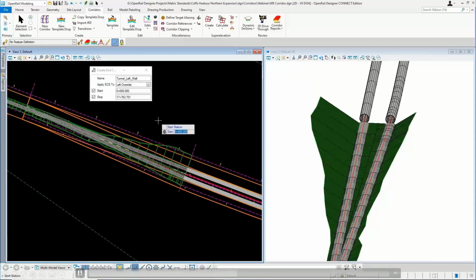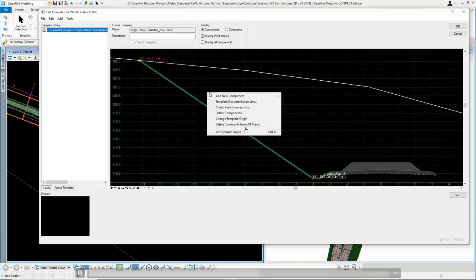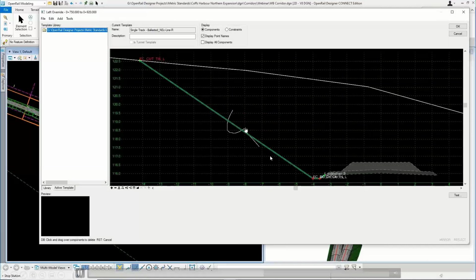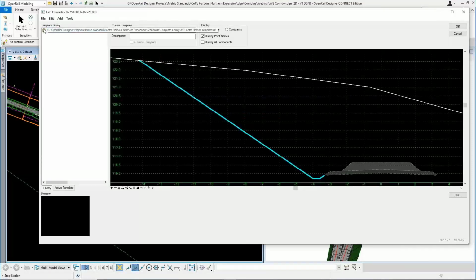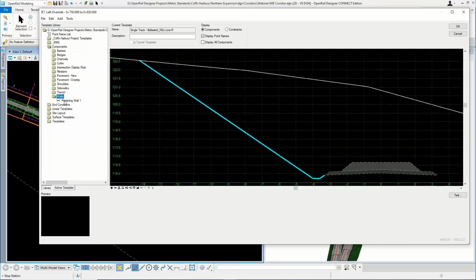Now what if you have to make an exemption in terms of how it cuts or fills your ground? Again, we have some tools that will allow you to apply a retaining wall instead of having a large cut in your existing ground, because of course too much cut or too much fill entails cost.